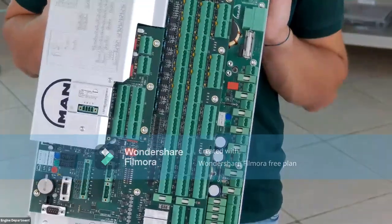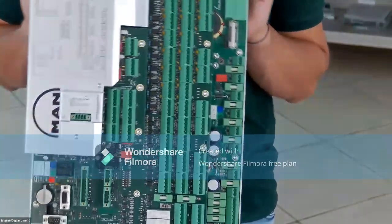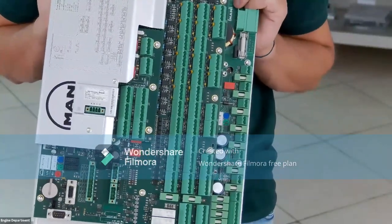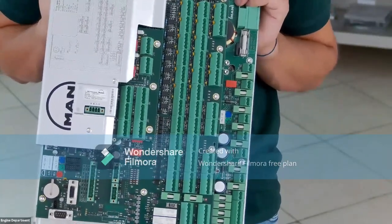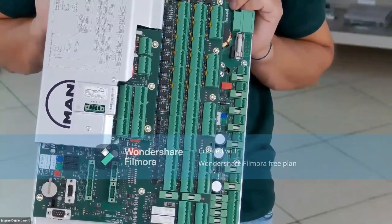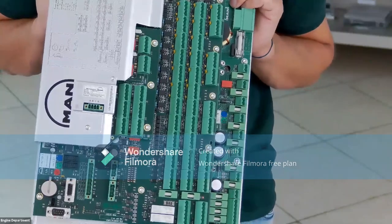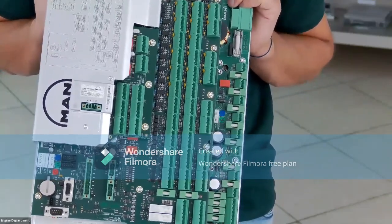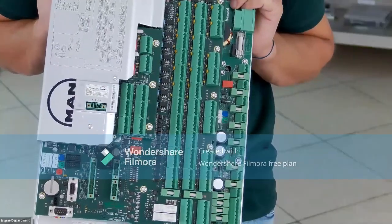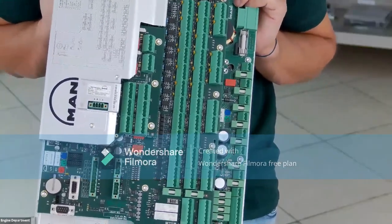So gentlemen, when you don't know the provenience of any MPC, so you find the MPC in your store without any information about it, is required to perform a force download. What is force download? Is required to ask manually to the MPC to erase the previous software and to install the software according with the ID key, actual ID key, which will be connected to the MPC. Is it clear?